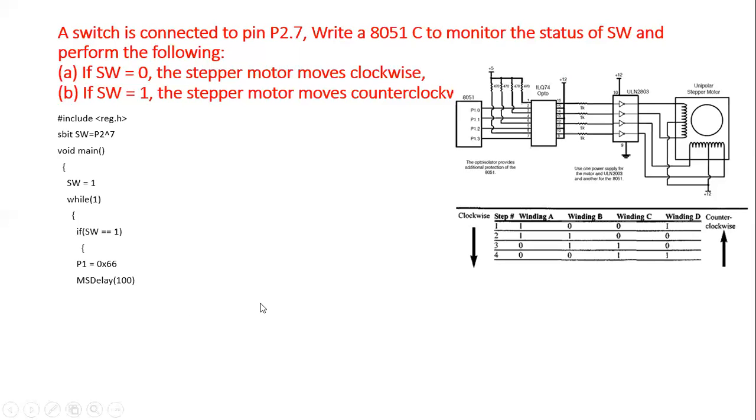So here I have a subroutine called ms delay, and we are passing this value 100 into it, which is able to receive unsigned integer values, so the 100 will be taken here. Then we have the local variables declared here, int x and y, and two nested for loops.